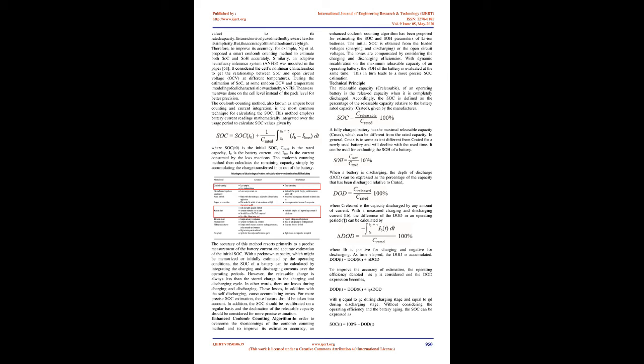1. Coulomb counting method. The Coulomb counting method is associated with monitoring the input and the output current continuously. Since capacity is the integral of current with respect to time, by measuring the input and the output current, change in capacity or capacity degradation of a battery can be measured easily. And this method's SOH is calculated by dividing the measured capacity, after discharging the battery to 0% SOC value, by its rated capacity. It is an extensively used method by researchers for its simplicity. But the accuracy of this method is not very high.